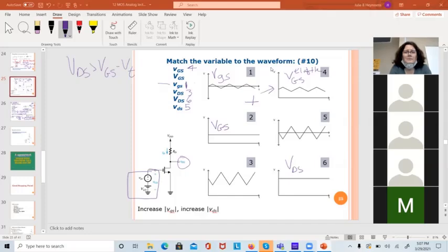Okay. So what you did is you generated what's called ESD, electrostatic discharge. If you rub your feet on the carpet and you touch the doorknob, you get a spark. That can be modeled as a voltage, and if you can feel it, it's like 10 kilovolts. It's a very high voltage, but it doesn't have any current drive capability.